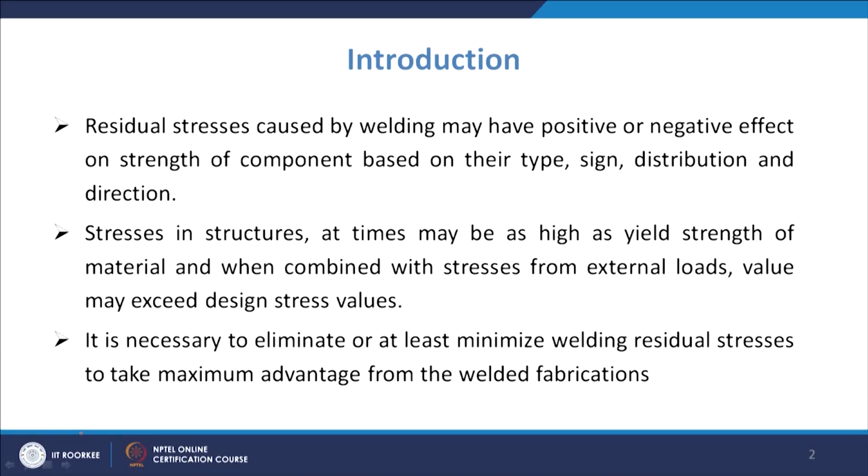Many times the stresses in the structure will be as high as the yield strength of the material, and when combined with stresses from external loads, they will go beyond your designed value.